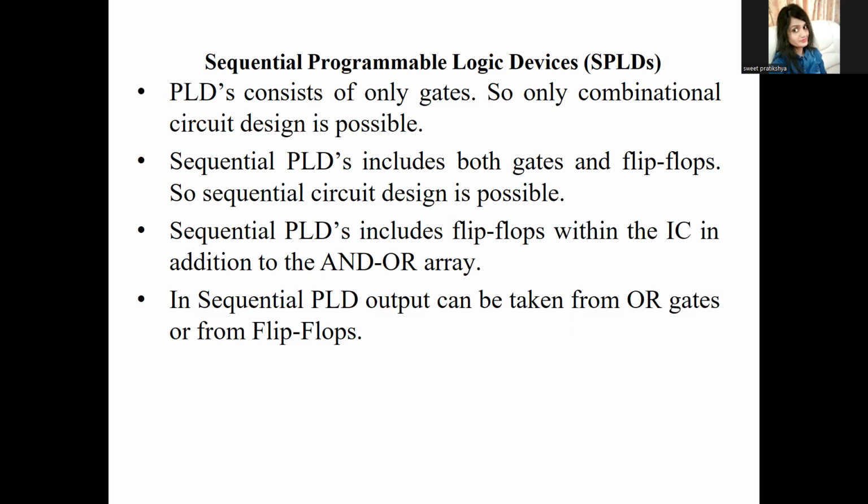As we saw, a PLD consists of only gates, so only combination circuit design is possible. But coming to the SPLD internal structure, they have each block called a macro cell. Each block contains combinational AND or OR logic and a flip-flop, either a JK flip-flop or a D flip-flop, and a multiplexer for output control. That means the output can be controlled in the SPLD device by using a multiplexer. Overall, this setup allows both combination and sequential logic implementation in one unit. So SPLDs are far better than PLDs.